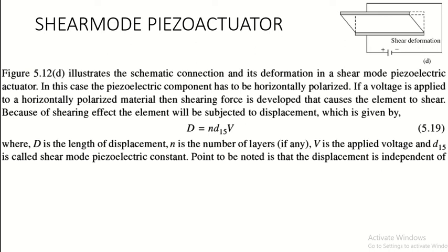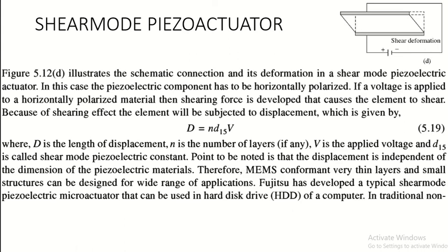One point to be noted is that displacement here is independent of the dimensions of the material we are using. Therefore, in case of MEMS, very thin layers and small structures can be designed. When we come from macro to micro level, the dimensions of a piezoelectric material are definitely going to change, but here those dimensions do not affect the basic working of the piezoelectric actuators.